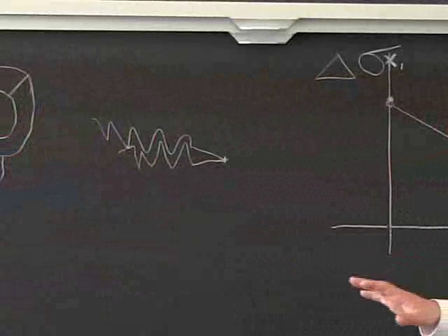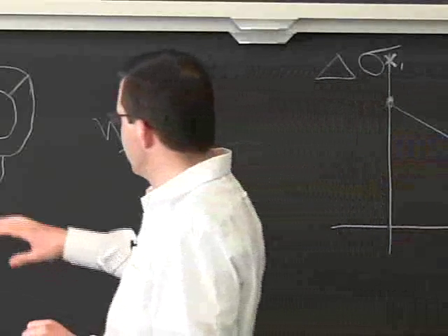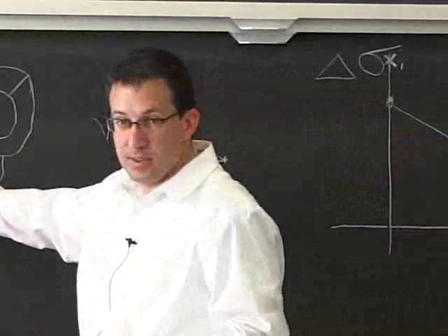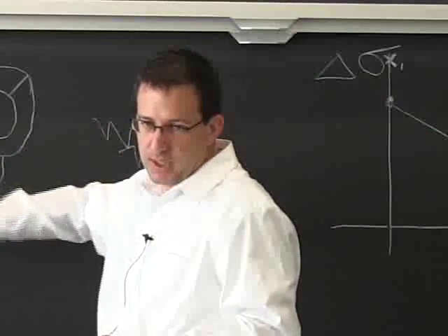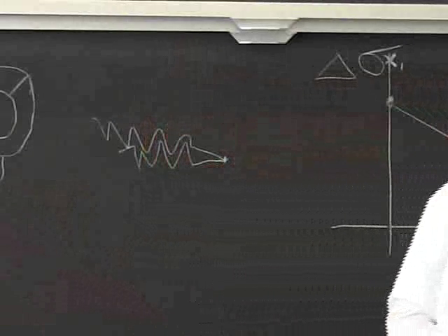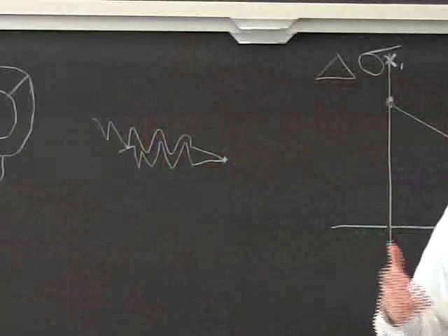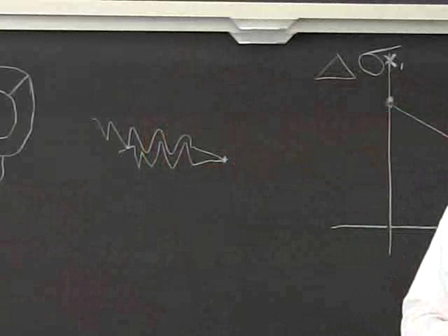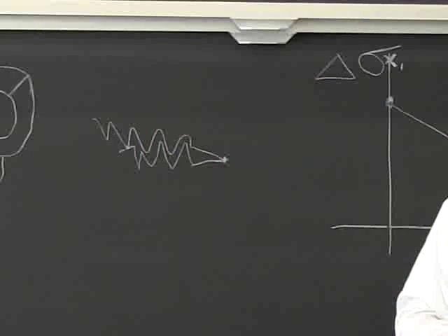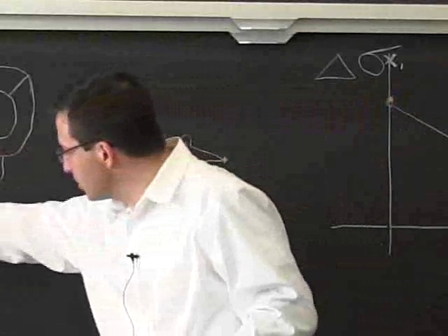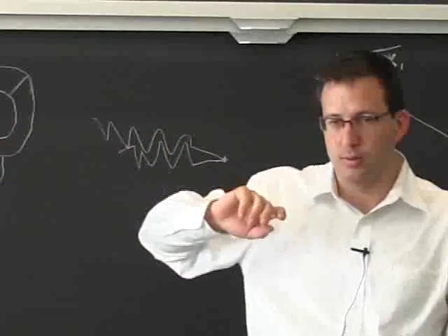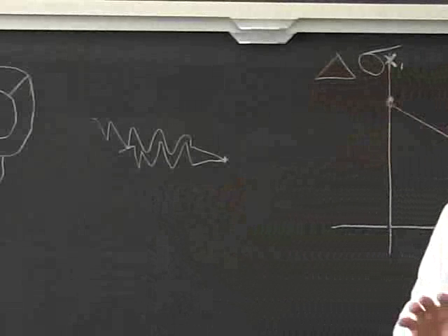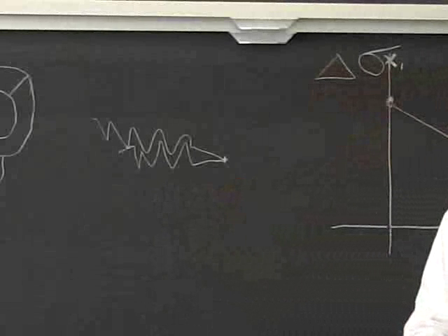If you're doing the design, this is the compression side, you may need to make this one thicker than this one, and it will essentially relate to your overall amount of material you're going to need. So the way I did that specific project, and there are many ways to do it, I said, look, I need about the same amount of area for my tension and compression zones, so I'll design them separately and then try to put them together.